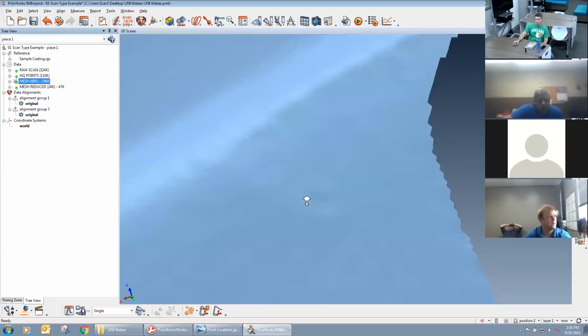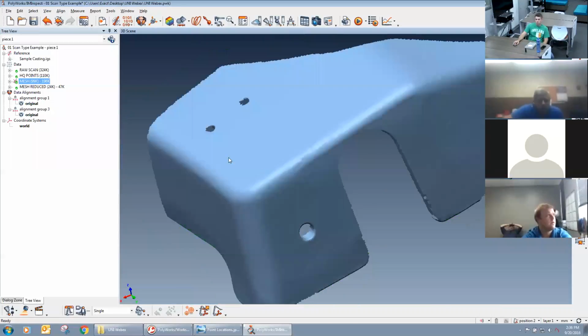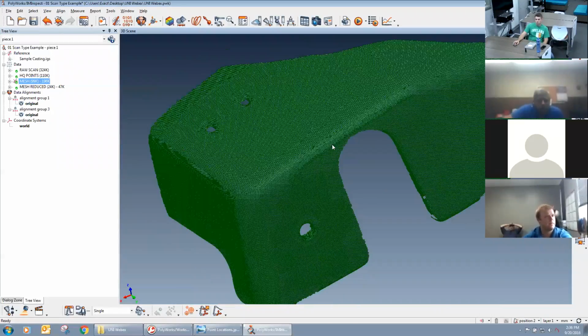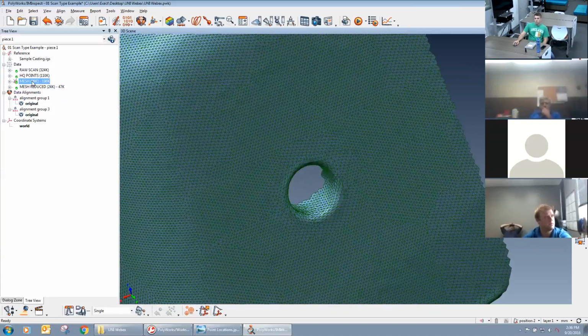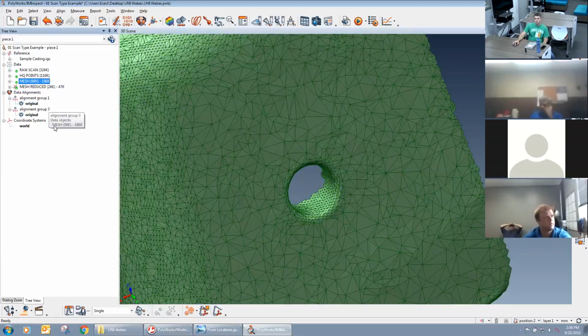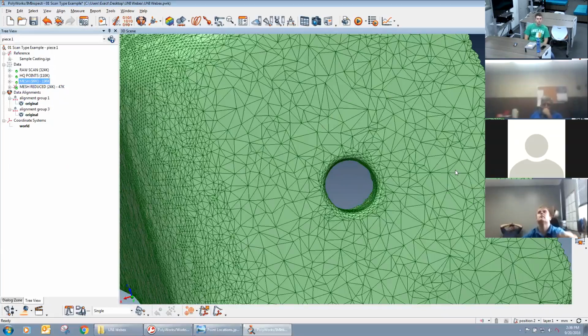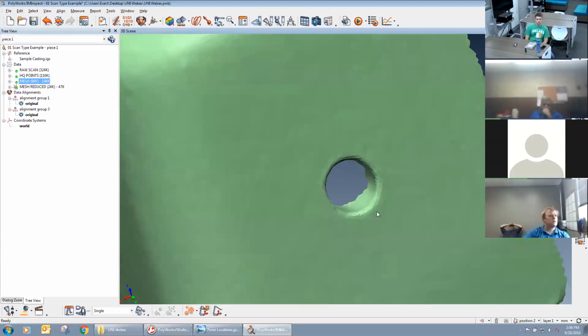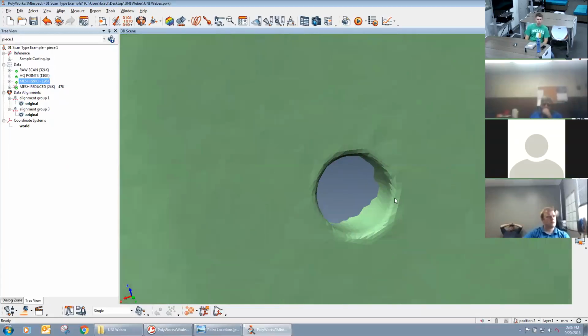But in the meshing algorithm, when you complete the mesh, there's an algorithm that runs that will reduce the size of these triangles based on the geometry. So that's my next one here. If you look at the triangles, it decided that on the flatter surfaces it can make larger triangles, but down here in the details, it retains the tiny 0.4 size triangles.